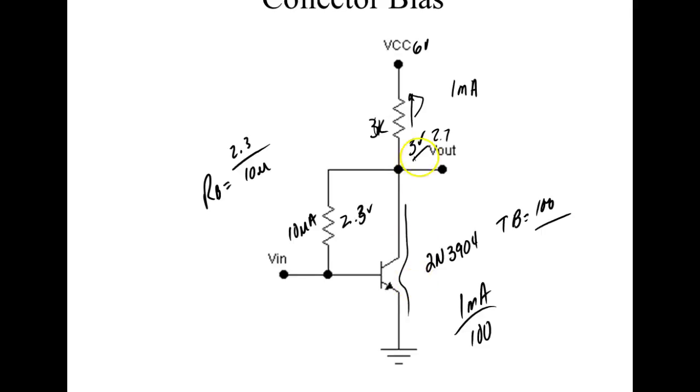Okay, so let's say this guy here drops 3 volts. Now, this 10 microamps is depending on this right here being 3 volts. This is going to drop 7/10 of a volt, less of whatever that is. So that right here is depending on this right here to be at what? This right here to be at 1 milliamp. Base current is setting the 1 milliamp. If base current goes down, IC goes down. If base current goes up, IC goes up. Y'all understand that? Ain't just neat?